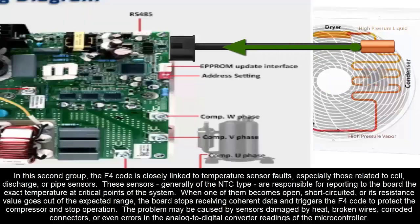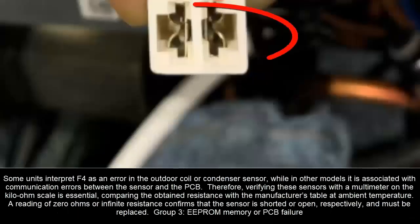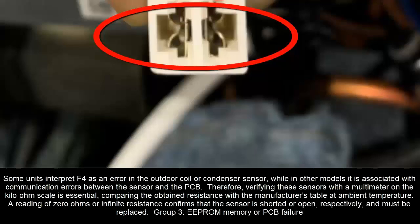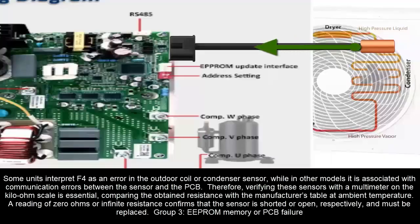The causes may be due to sensors damaged by heat, broken wires, corroded connectors, or even errors in the analog-to-digital converter readings of the microcontroller. In some models, F4 is interpreted as an error in the outdoor coil or condenser sensor, while in other models it is associated with communication errors between the sensor and the PCB.